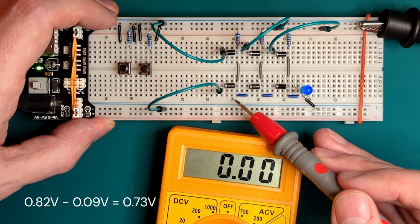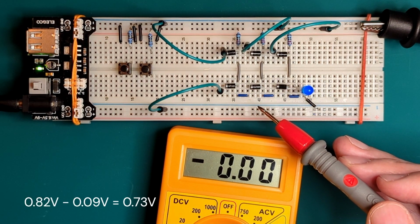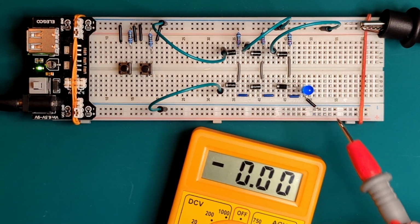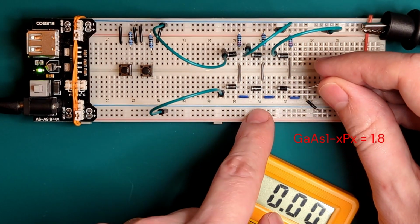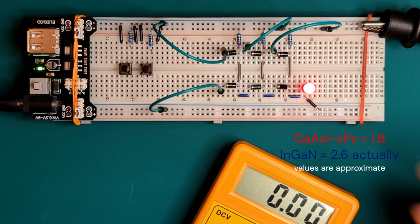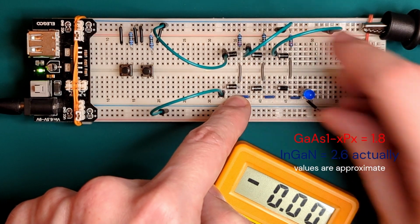My regular diodes are silicon, which usually drops about 0.7 volts, and each color of LEDs has a different chemistry. My red LEDs are gallium arsenide phosphide, which have a typical drop of 1.8 volts. And my blue LEDs are gallium nitride, which has a drop of 2.4 volts.